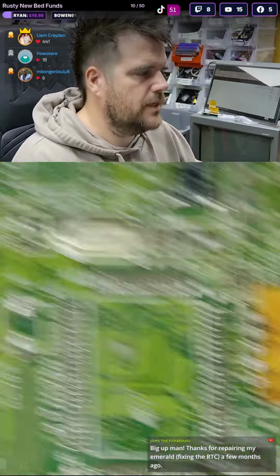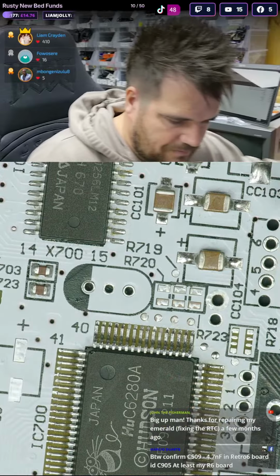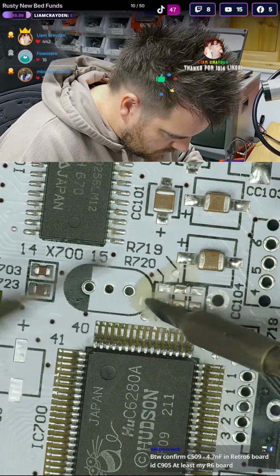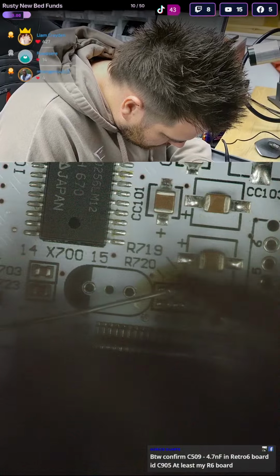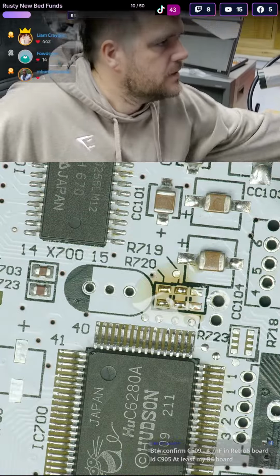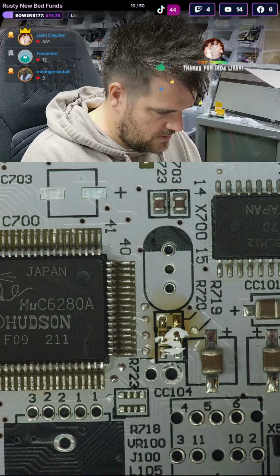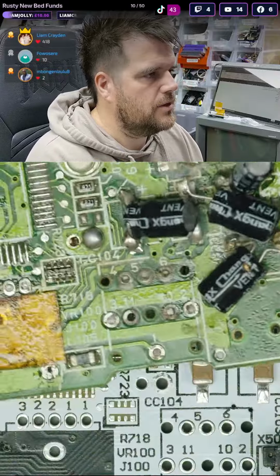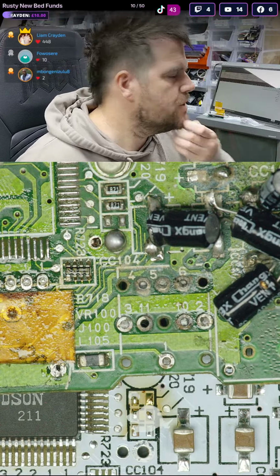And then all we have to do is prepare these pads here with flux and solder. And again, let's try not to put too much solder on the pads because the resistors are coming off the other board with a little bit of solder already on them, and they end up bubbling up. So tiny bit on there. We'll put that way, get this board that way. There we go. And then we'll just hot air them off. I don't know whether you can see both just about there. Just about fitting both in frame.